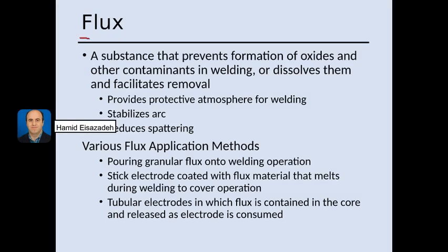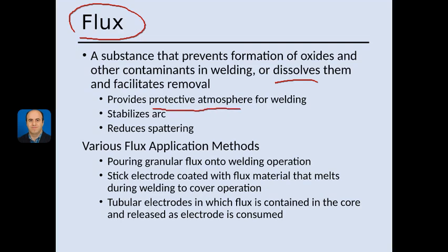The next term in the welding process is flux. Flux prevents oxidation or other contamination in the welding process. Sometimes it can dissolve this oxidation during the process. The main task of flux is that it can provide a protection for the filler material or the weld from air contamination.